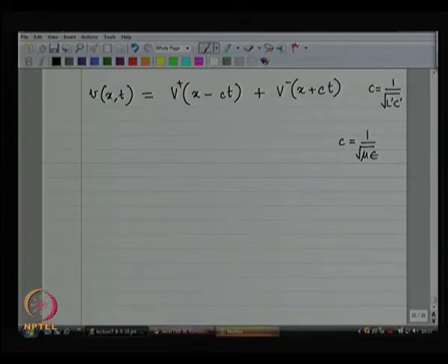We just hand waved our way and we said one is an inductance per unit length, one is a capacitance per unit length. Really what is happening is that an electromagnetic wave is propagating over the piece of wire, and the speed of that wave is a known quantity. The speed of that wave is 1 by square root of mu times epsilon. Okay. All of these are actually coming from Maxwell's equations, and we are reformulating Maxwell in our own convenient way in terms of voltages and currents.